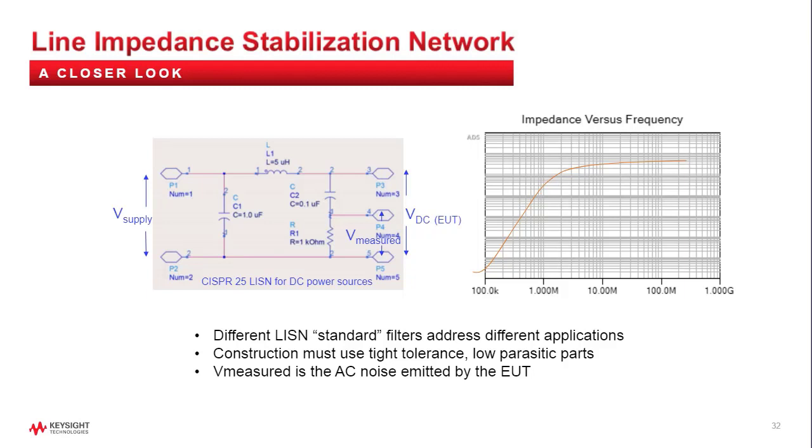It's a pretty good sized piece of wire. It handles 20 amps in a household circuit, 50 feet long. And it's shocking to me that a 4-inch plane of 1 ounce copper is equivalent to a 12 gauge wire. So what this means is when you look at these power modules and these power distribution networks, 1 ounce copper can carry a lot of current without struggling at all. So keep this in mind. We'll have another question later related to this.